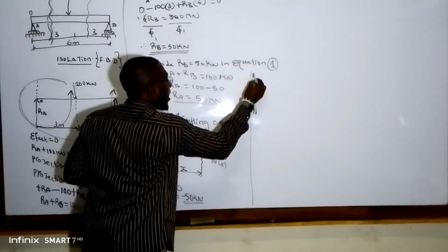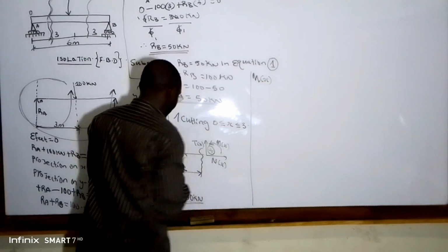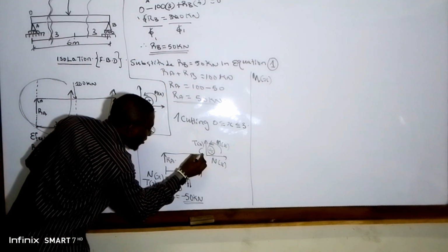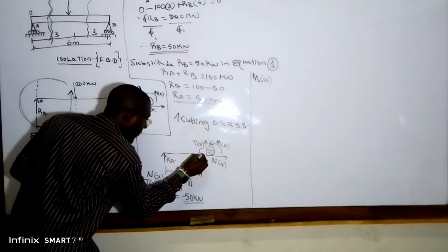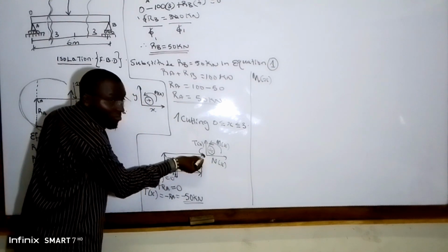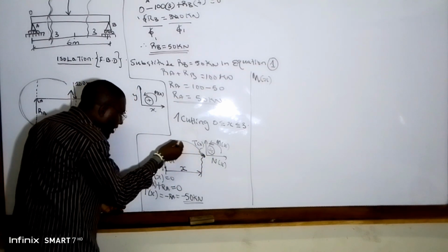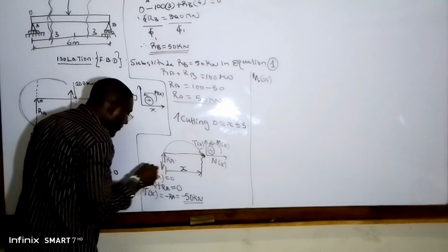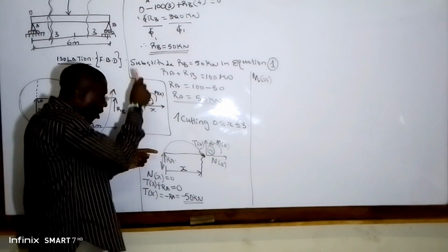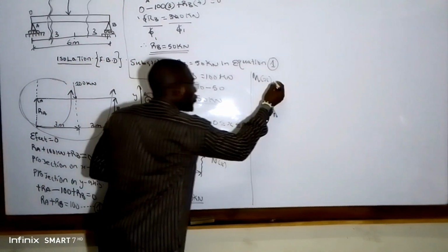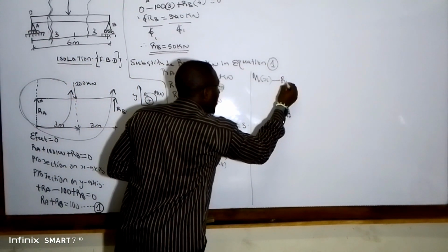Let's look for our M of x. So guys, looking for the M of x, this is where your center of moment is, applied at this extreme end. Our moment is rotating like this, and this force is going up. So it is acting in an opposite direction to the orientation we have chosen, so it receives a negative sign.